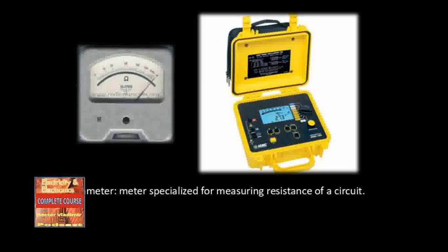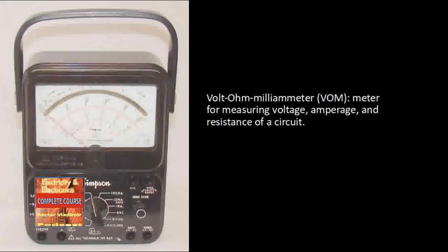It is best to disconnect the voltage source before taking any resistance measurements. In general, it is not necessary to observe polarity when taking resistance measurements. However, as you advance through your studies, polarity must be observed when checking certain solid-state devices. Always adjust and zero the meter on proper range before measurements are made. The ohm meter should be readjusted after changing ranges or after prolonged use. An open circuit will have an infinite reading.